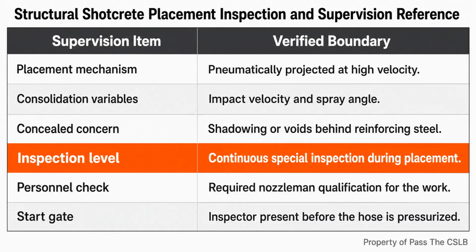The Shotcrete reference table contrasts the field conditions that matter. The nozzleman controls the live angle and distance. The material is consolidated by impact. Reinforcing steel becomes concealed as thickness builds. Because the critical workmanship is happening in real time, the inspection must follow the operation in real time.